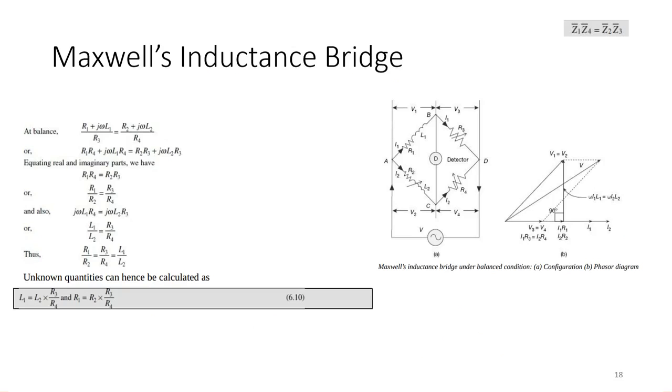Now let's explore the same bridge for phenomena where we calculate the capacitance and inductances. The Maxwell bridge is used for calculating the inductance, and it's a bit simple, because we have a variable inductor and a variable resistance in it, and we just use the balance condition Z1 divided by Z3 is equal to Z2 divided by Z4, and put in the values.